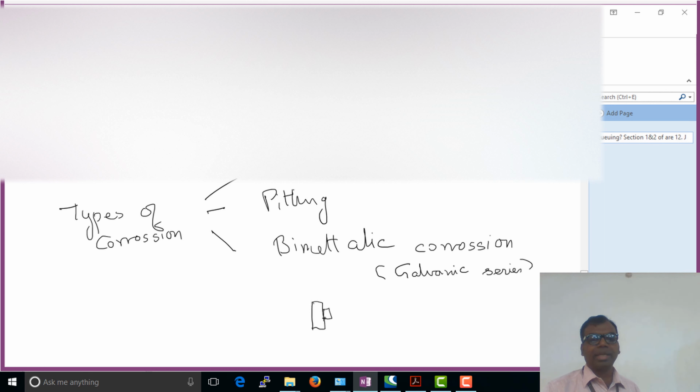bearing on the surface of the plate. After some time, because of corrosion, what happens? The products of corrosion would form and this place will totally get eaten away. Now after this, what happens to the connection? The connection becomes loose, in the sense that only as long as it's pressing against the other, you are going to have contact. You can still tighten it further to make the contact, but this is not going to help you in the long run. So this is a very important thing you have to consider when you are looking at connection design. Again, this pitting, when does pitting take place?